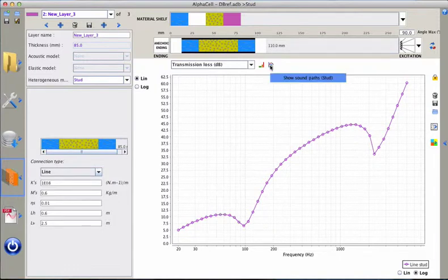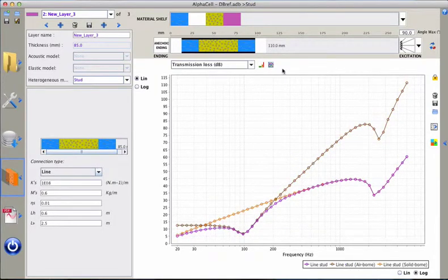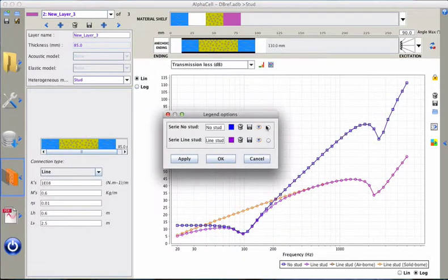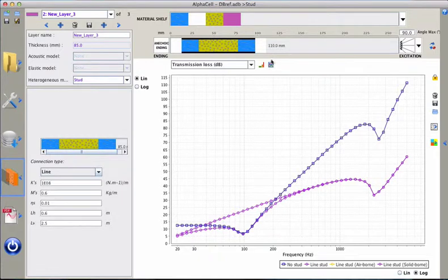just to show you here the path of the sound path. So we can here see the airborne and the solid-borne path to build our sound transmission loss. And we can see that our transmission loss is the result of this airborne and structure-borne path. And we can also see the effect, of course, of the studs on the sound transmission loss.